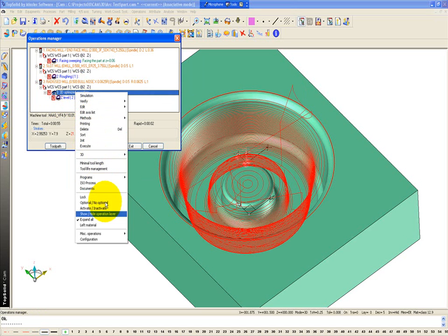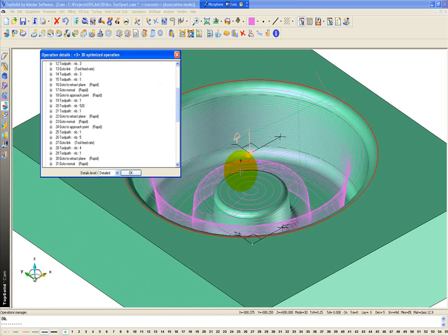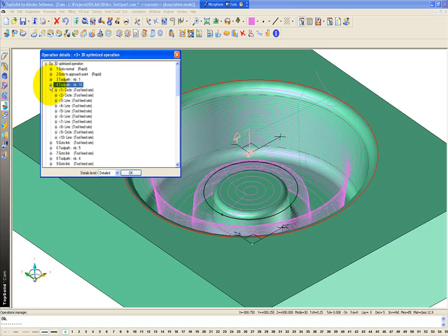Toolpath looks the same. If I go in here back to Details, again, you see your approach point, right? Wrap it down. Now in this case, instead of plunging down, it's arcing on. And now here's our toolpath link. And now here you can see we're cutting segments of circles, some lines, another circle, another line. And that's using the same tolerance of programming. Okay? So there's 10 lines of G-code that'll be output to do this first circular toolpath.